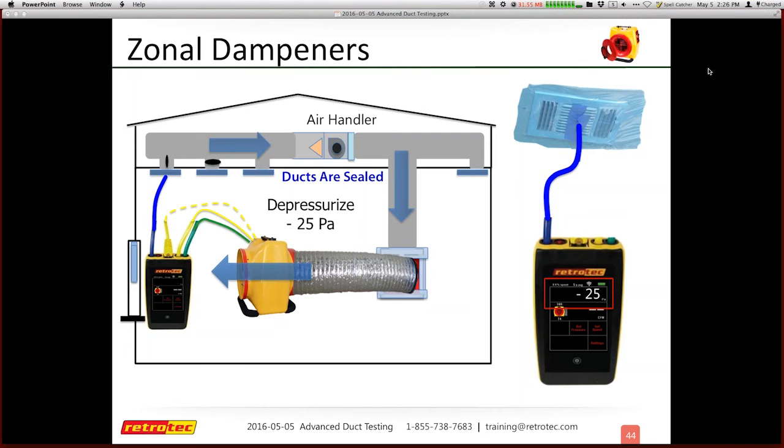Again, the whole system is sealed, so when it does open up, and I know it's open, I'm getting pressures inside this individual duct. And I go to the next one and realize that one is still closed. I can go to another one and find out it's open. So your goal is to make sure that they are all open, obviously, when you're doing your test. And some systems are in their natural state open. Some are in their natural state closed.